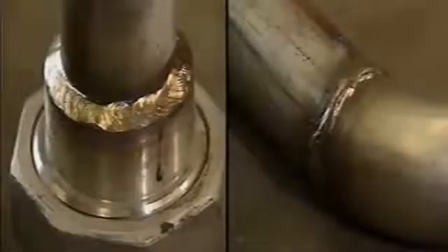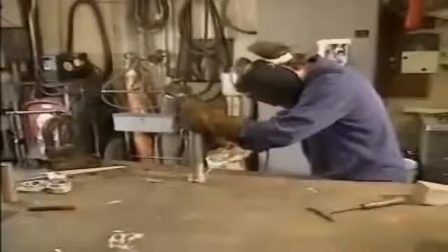There are two types of welded pipe joints: socket weld and butt weld. In a socket weld joint, a pipe is inserted into the socket of a fitting that has an opening larger than the pipe's outside diameter. The edges of the socket are then welded around the outside of the pipe. To create a butt weld joint, the beveled end of a fitting is lined up with a pipe. Then the edges of the joint are welded around the outside of the pipe.